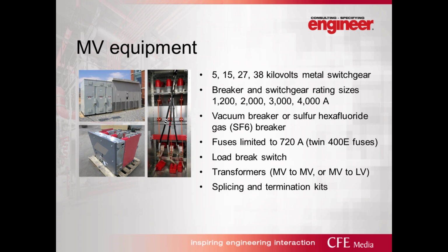Another piece that's often with medium voltage is lightning arresters. Because medium voltage is coming in, there's generally no isolation transformer. So to protect from surge and lightning strikes, you'll add lightning arresters. And that picture there shows a medium voltage termination and the lightning arresters in the back of a medium voltage switchgear.